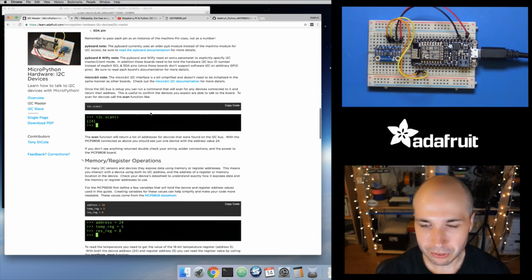you're pretty much set. Now there's a really cool thing with I2C. Like I mentioned, every device on the I2C bus has an address assigned to it, and it's just a 7-bit value, so 0 to 127. I think the first few values are reserved, but mostly about 100 devices can be connected to the bus. Now that is a limitation. You cannot have more than that 127 uniquely addressed devices on the bus. It's just not physically possible. If 2 devices have the same address, you're going to get a lot of confusion. Each one's going to try and respond to the same thing, and bad things will happen.